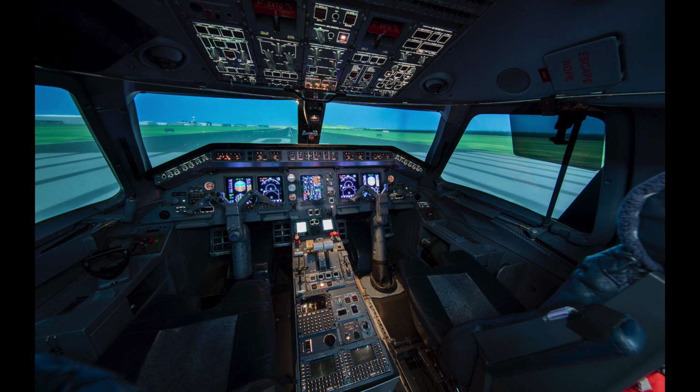The next call comes from the pilot monitoring, positive climb. Again, a critical call. If you forget that call, we will more than likely forget to put the gear up as well. So, positive climb, gear up. We wait till 400 foot AGL. At 400 foot, we select heading, and we will see on the FMA heading in green, so we call heading green.